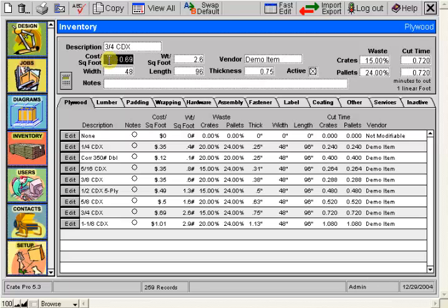Likewise, the weight is also per square foot. Crate Pro uses what we call rules to determine the appropriate spacing for intermediate cleats. Some rules are based on the size of the plywood, so Crate Pro requires the material dimensions. When designing a crate, you can also modify the cost of the crate by adjusting the plywood yield. To do this accurately, you need to know the material size you're working with.